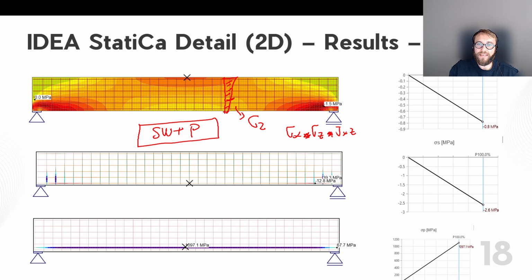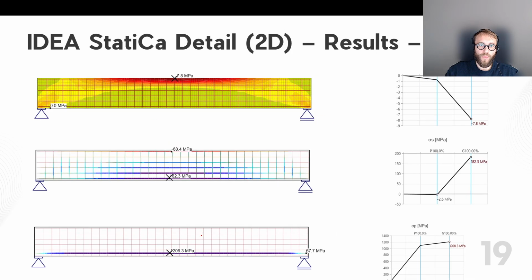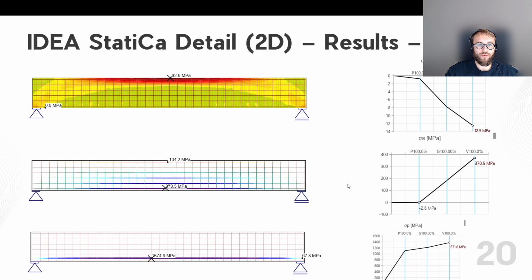Of course, there is a combination rule for the principal stresses that you need to account for, but those three components of stress are stepping into the final outcome, which is the critical maximal principal stress under compression. So, what about the tendon? Tendon stress is 1097 megapascal, and we can basically move forward.